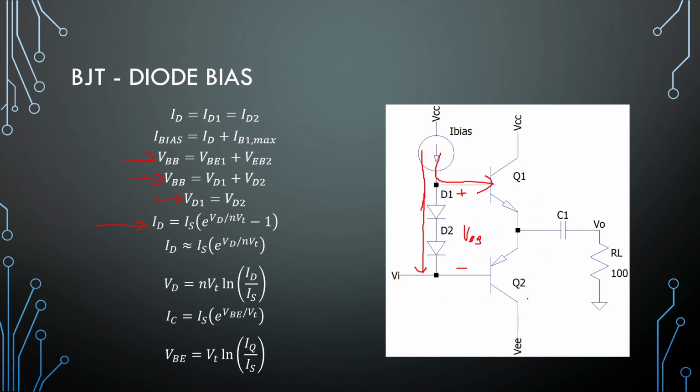We would switch these transistors on at a very high current, and it would be pointless because we would have great losses or too much current flowing in these transistors, burning them, or in general, it would be bad. So we need to precisely calculate the diode voltages and our transistor on voltages right here for a specific current.